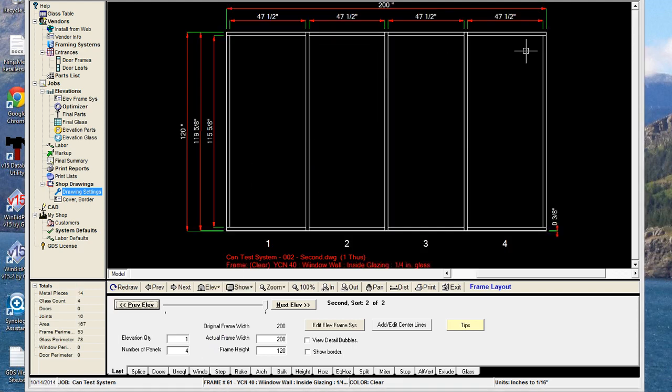Okay. So once again, the way they drew it was to have the wall jambs in between the head and sill, basically, so that they're not interrupting, and the verticals are interrupting. So not sure why YKK would call this a can system. This is why it's important to know how to configure it on your own, because a lot of times we'll have the manufacturer set up a catalog for us.